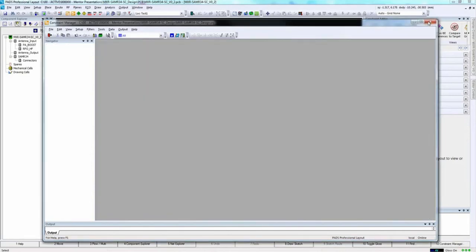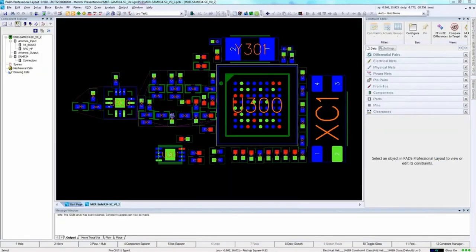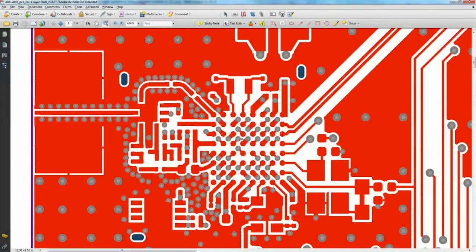Now, it's also important to remember that when we are looking at a design like this, if we go back to our finished layout here, right angles in a trace can cause more radiation. The capacitance increases in the region of the corner, and the characteristic impedance changes. So this impedance causes reflections. So we want to avoid right angle bends in a trace and try to route them at least with 45-degree corners to minimize any impedance change. Best routing would be a round bend like we see right here.